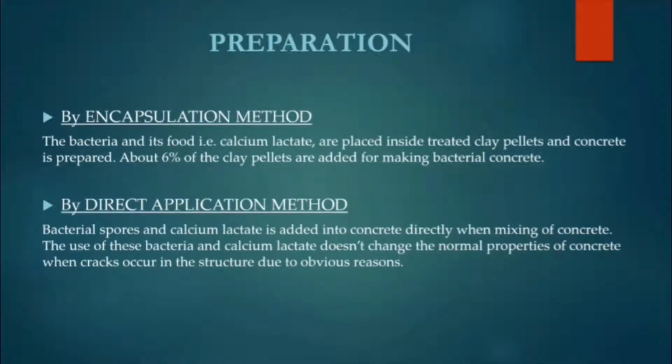Preparation. There are two methods of preparation of self-healing concrete. The first one is the encapsulation method. The bacteria and its food, that is calcium lactate, are placed inside treated clay pellets and concrete is prepared. About 6% of the clay pellets are added for making bacterial concrete.